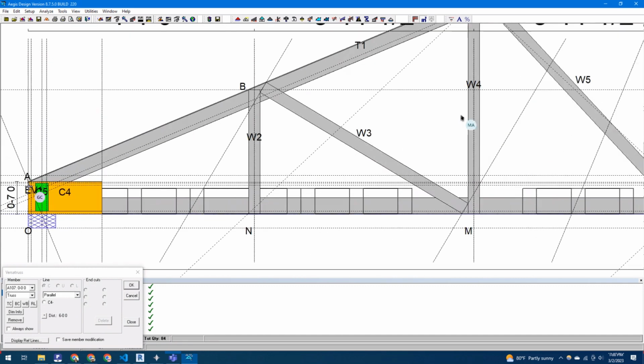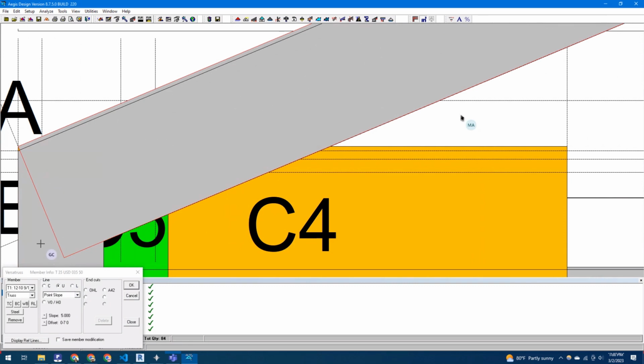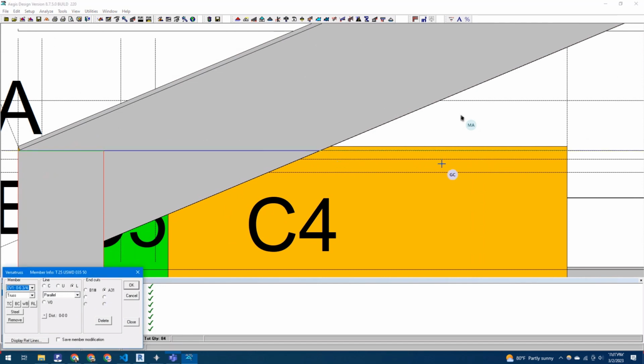It's up there. Okay. So now I would pick this piece here, not that one, this one. And I have two end cuts. This one's telling me that this is cut to the upper edge of the flange on the bottom chord. So it says B1 sharp, or hashtag, which anytime you see the hashtag, that represents the edge of the lip on the material for the chord. So I know I can't change that one. So A31, see it highlighted here.